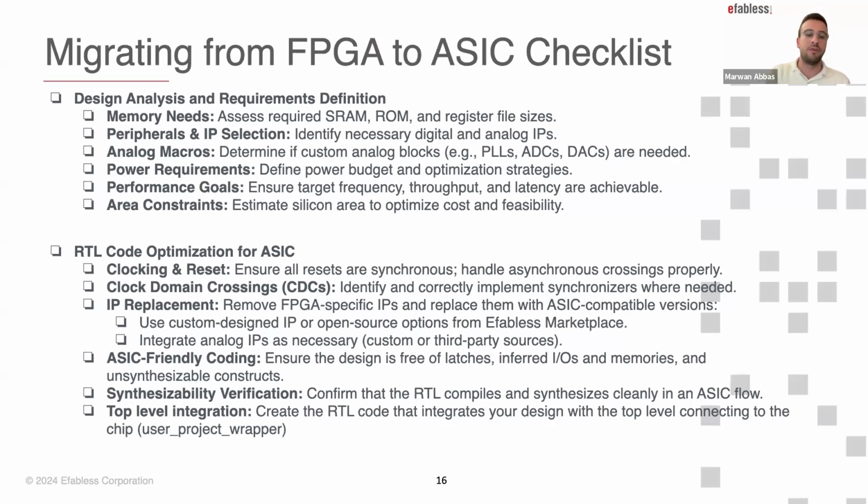And moving to power and performance. In FPGA, power consumption is already predefined for you, but in ASIC, you can customize it even further. You can implement some techniques such as clock gating or power gating that would customize your power for your specific needs and your design's needs.